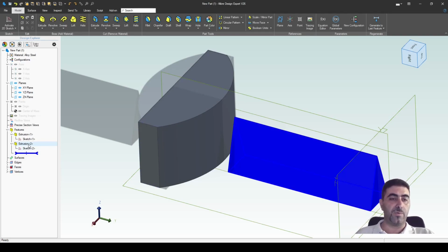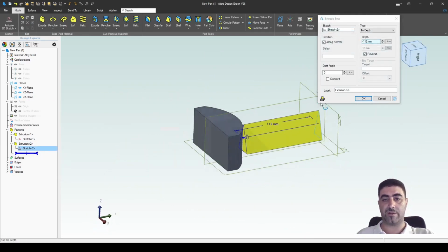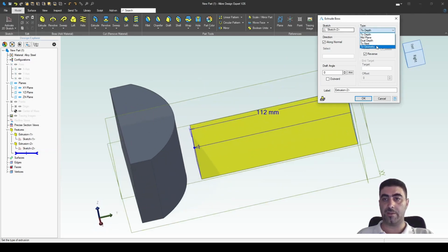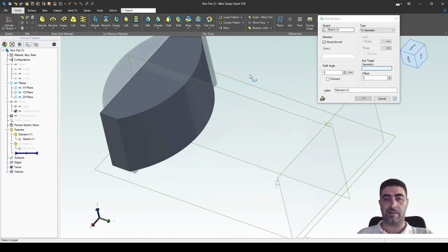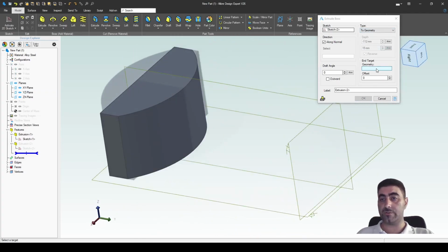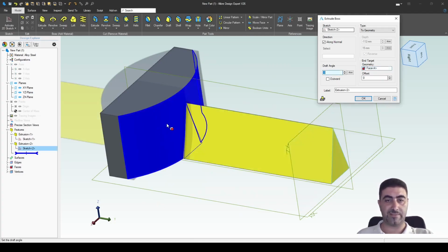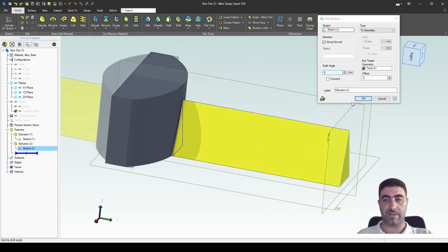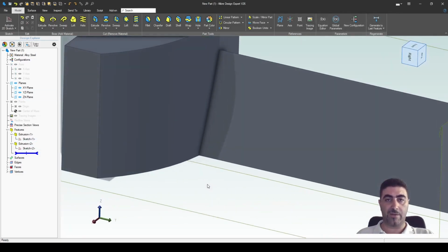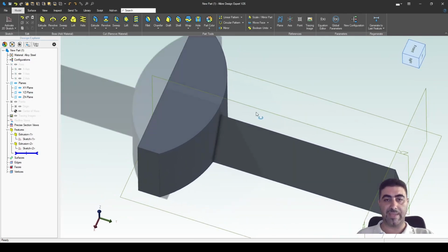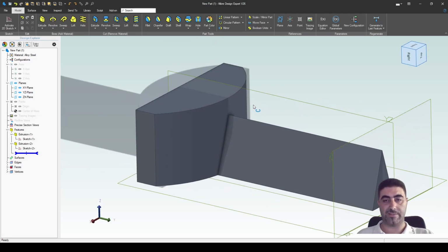So if we go back to the second extrusion and use that option we were talking about, the to geometry option, well, the preview goes away because the system is asking us for a geometry target. Now let me select this. I click on that, hit OK. Look what happened. Okay, now the end of my extrusion is no longer a flat face.